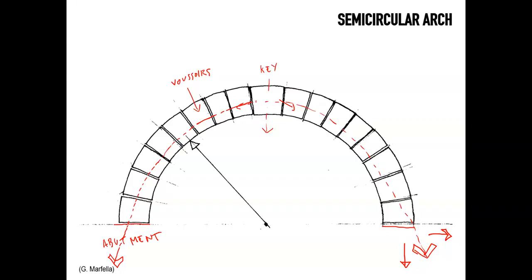Now, the semicircular arch is not necessarily a natural curve that will result in the distribution of gravity, but it is a practical shape that is very easy to set. Like anything that is circular, it just requires a fixed point and an ability to rotate a constant length. In this process, it is, as we saw, possible to create centerings and geometries that derive from this, like the barrel vault, the groin vaults, and so on.